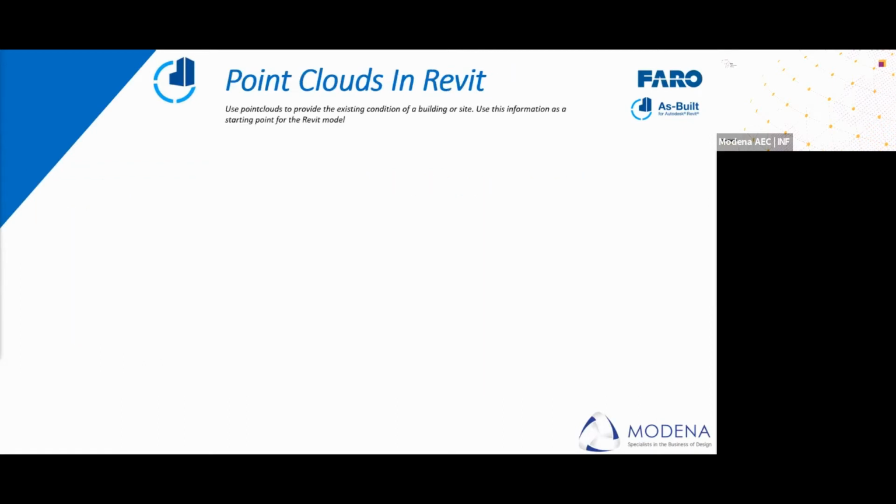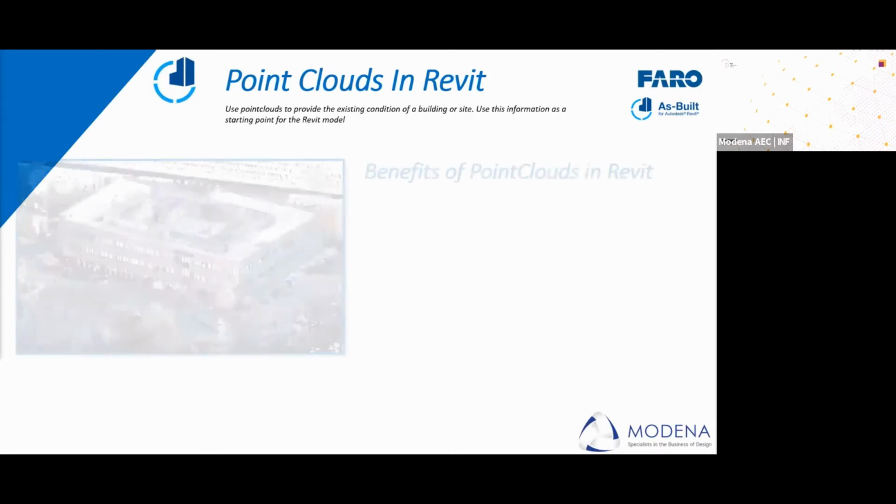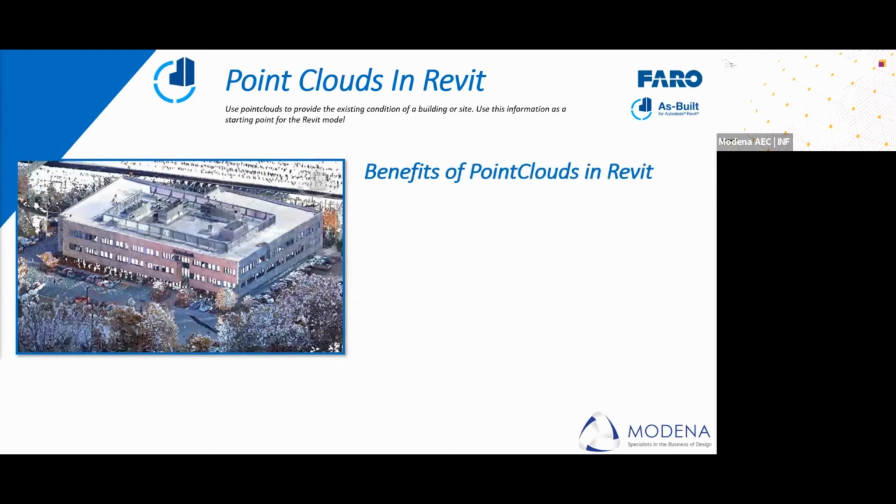Let's look at point clouds within Revit. So we use point clouds to provide existing conditions of buildings on site. We use this information as a starting point for the Revit model. So remember, our point cloud is a starting point. So benefits of point clouds in Revit. Well, the first benefit that we have is point clouds behave like an object in Revit.